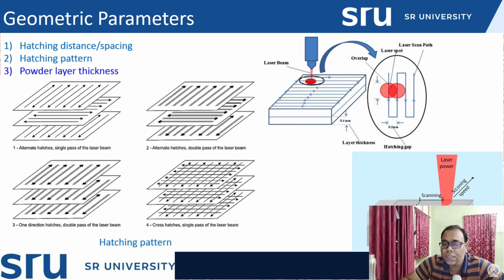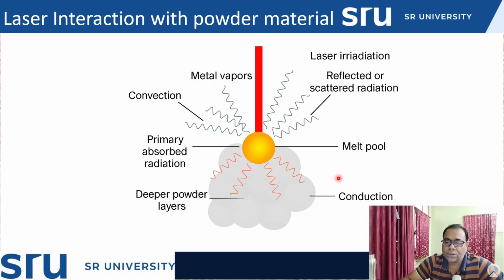And this is the one profile that will be there. So how will printing take place? We know that we are using a Gaussian pattern profile, so we can see that this profile is presented here, and from that one can understand. This is the substrate. Over that substrate, powder material will be spread and then scanning will take place, and then there is the scanning speed and similarly the scanning direction. And this is the laser power.